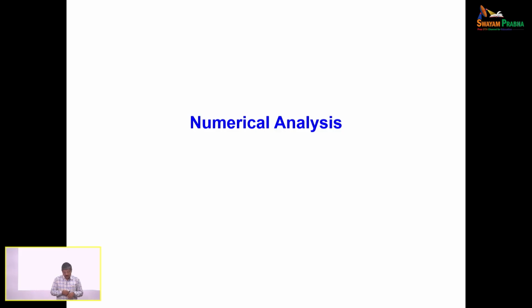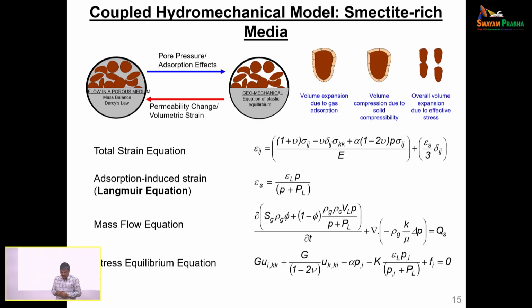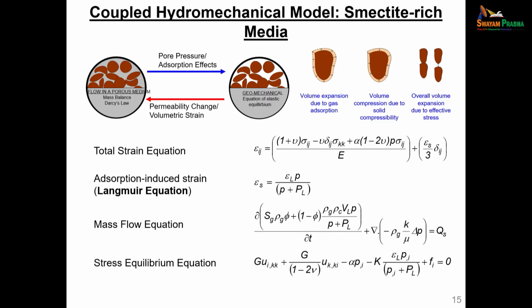The next part is something to do with this. Can we take the carbon dioxide into the deep geological media? Now the clay is filled in the fault. If it is exposed to different pressures and temperatures, how is it really going to respond? Let us try to understand that. Imagine that there is only pure clay alone, or maybe pure clay and quartz, in a dry state. When you expose this kind of system to the high pressure of CO2, possibly two things can happen. As I told you, because of the adsorption of CO2 on the clay mineral, swelling takes place. If you don't allow the swelling to happen freely,